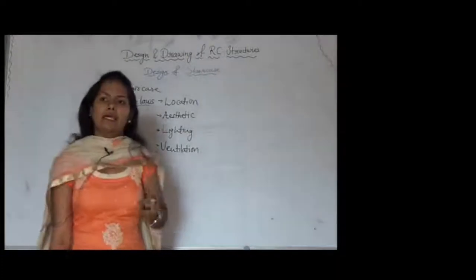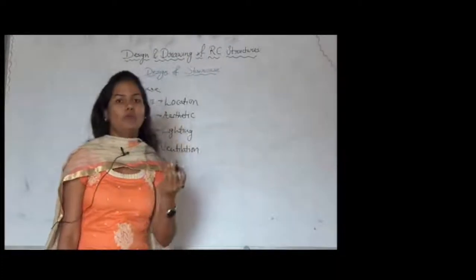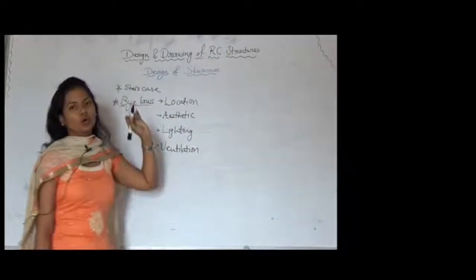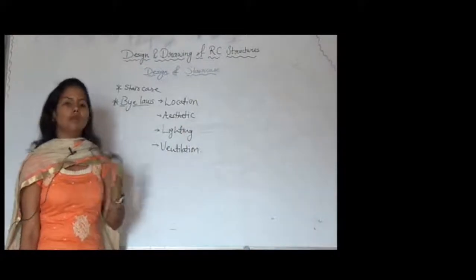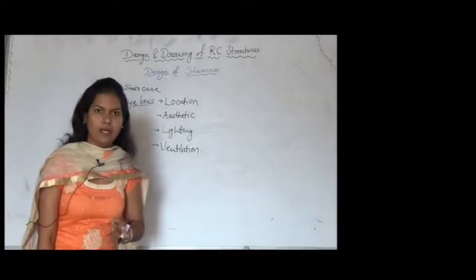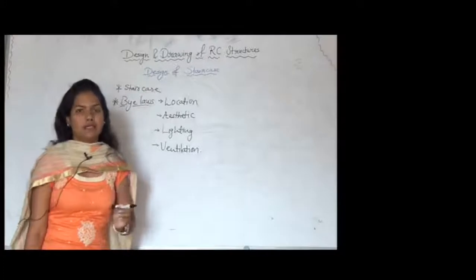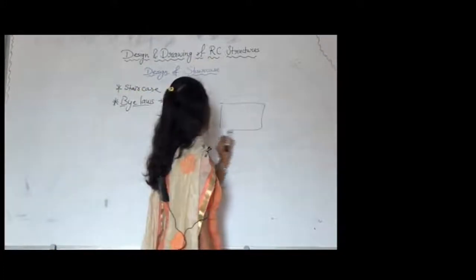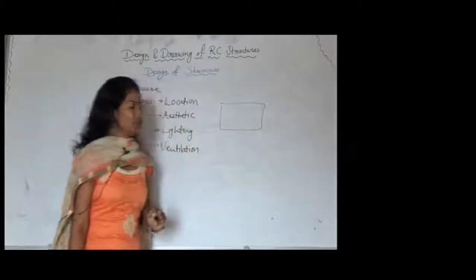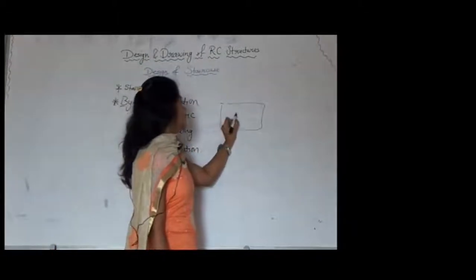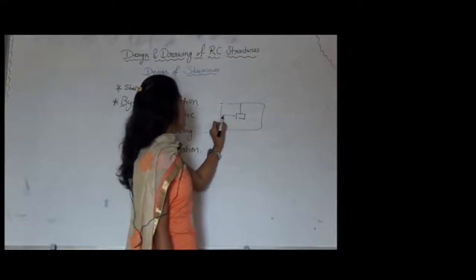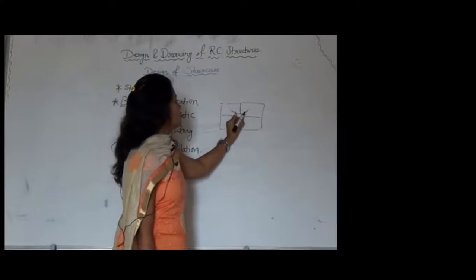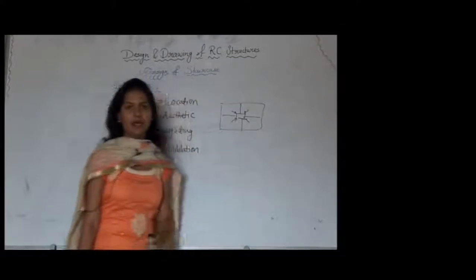Now depending upon the type of structure or type of building, we should know where the location of staircase should be. Now if we consider a residential building, then where should the staircase be? Definitely in any building, in case of residential, we provide it in such a way that from all the corners of the floor there is easy access to the staircase area.